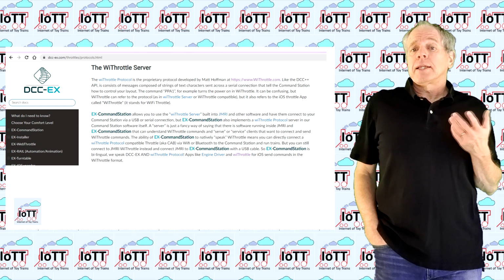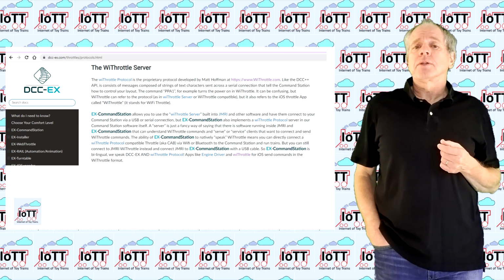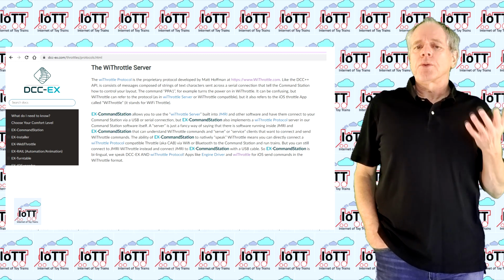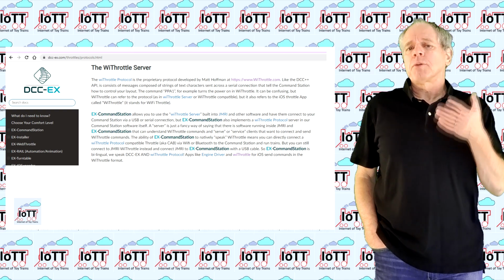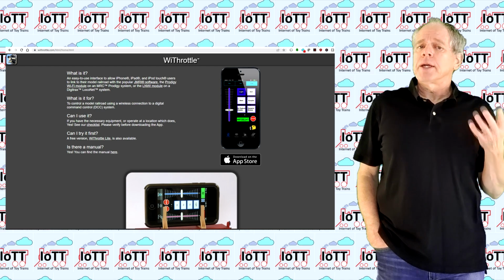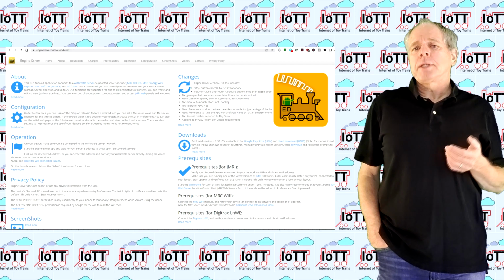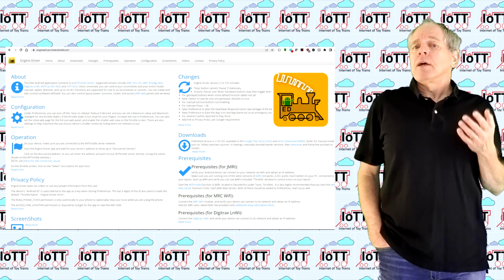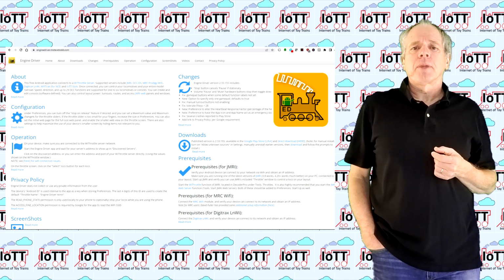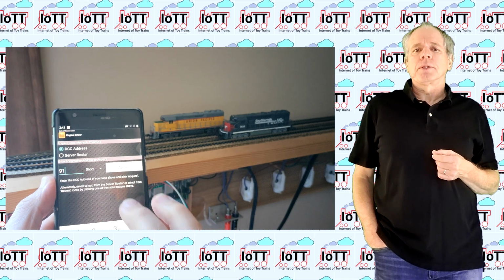The third server that is available on the IoTT stick when using Loconet is the WiThrottle Server. This is a protocol developed by Matt Hoffman to control locomotives and turnouts from a smartphone or tablet. Several smartphones can be connected as clients to a server, and currently there are two apps I know about that support it: WiThrottle for iOS and Engine Driver for Android. Both apps can be downloaded and installed from the respective app store.